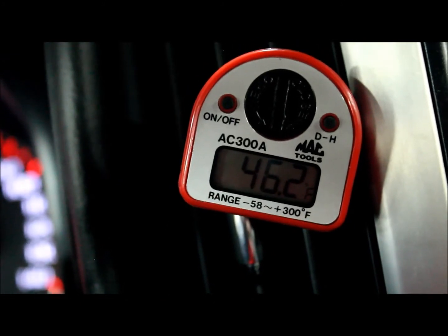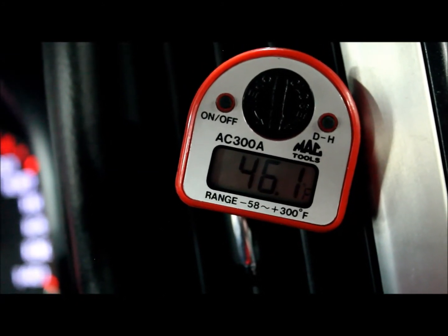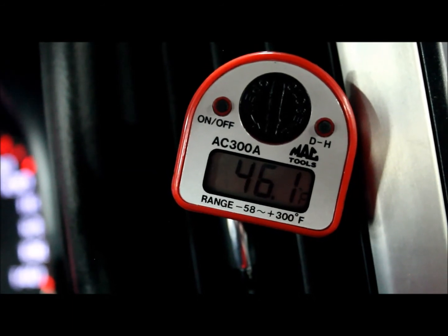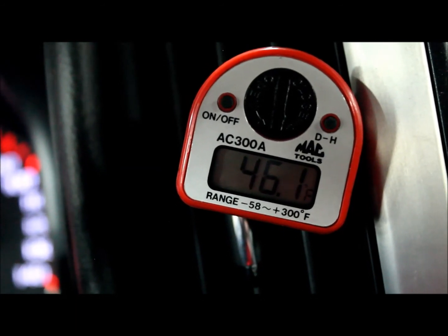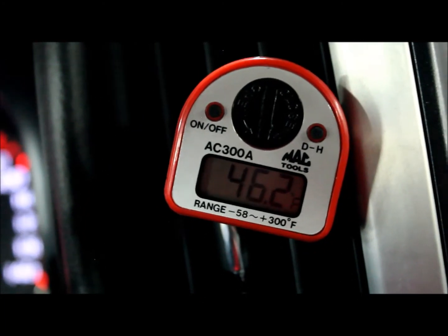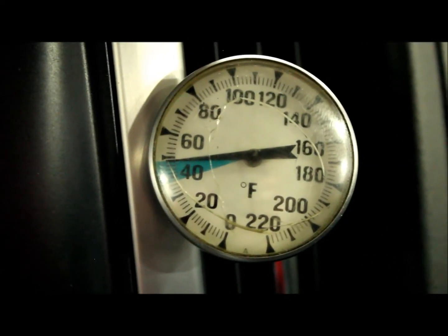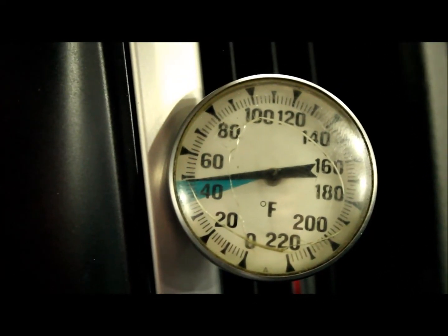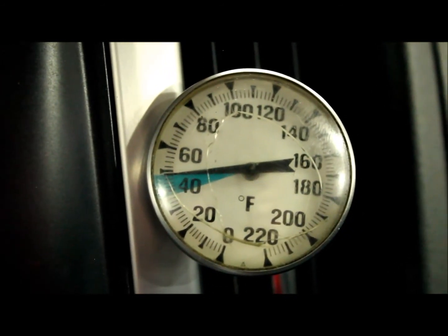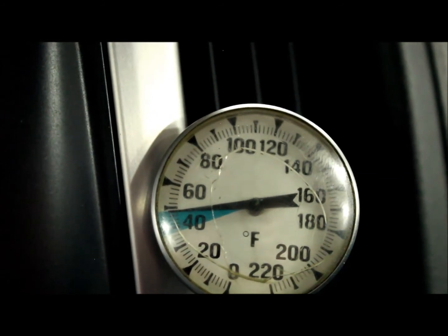Inside the vehicle, it's a little bit noisy with the AC running on max. Here is our left center outlet, 46.1 degrees Fahrenheit. How does that compare to the spec? Also, in case it was too hard to see the digital gauge, on the other side, I put an analog thermometer, and it's showing a little bit under 50. Not sure this is as accurate as the digital one, but it's just at the top of the green.